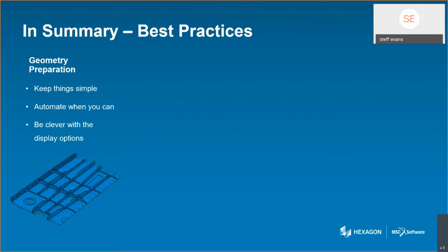And then thirdly, tip 3, be clever with your display options. So use auto color within the model browser and use transparency to compare your 3D geometry with your underlying mid-surface and shell mesh definition.